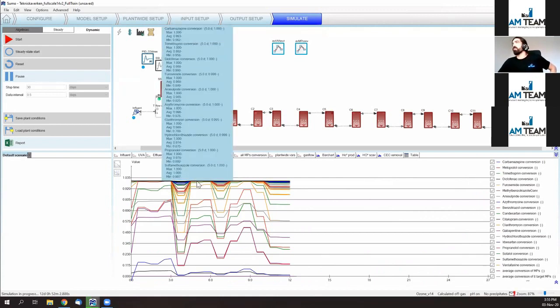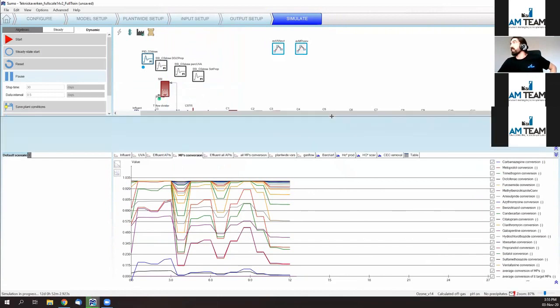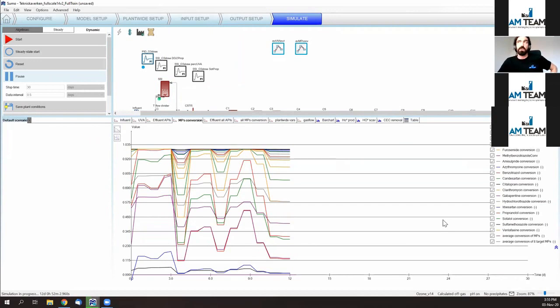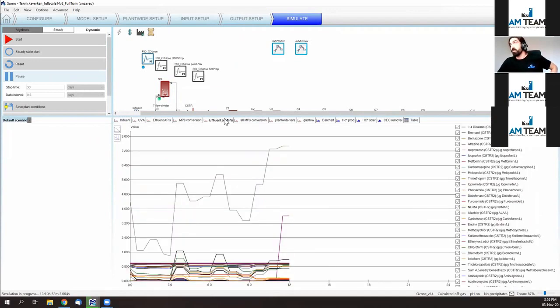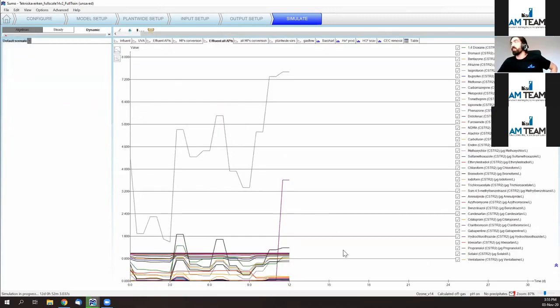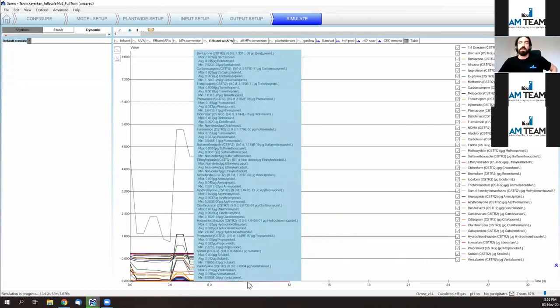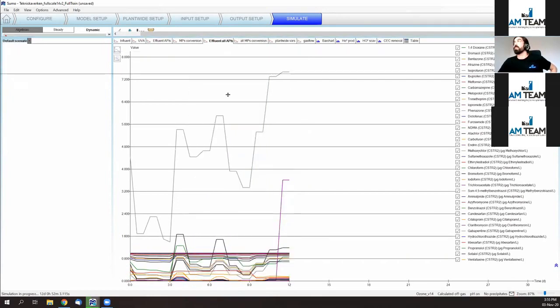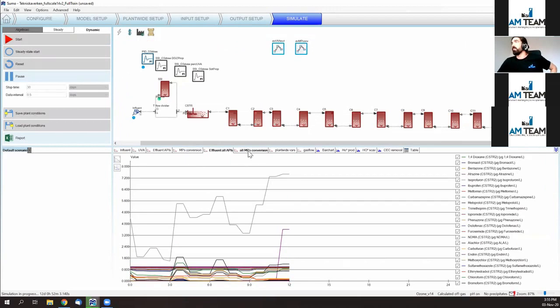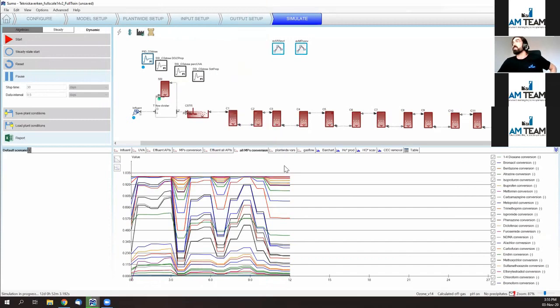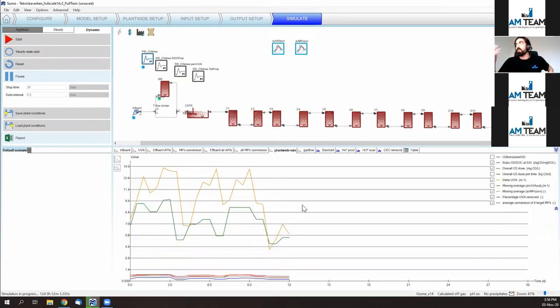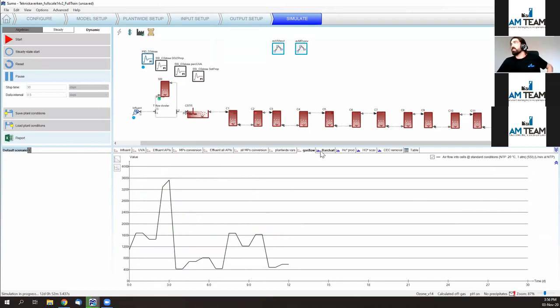You can still, as I was saying before, look at the conversion of the micropollutants that were here, to see the list of interest for this plant, but you can also look at a much larger list that we have implemented there. So you can really have a large variety of micropollutants and all sorts of compounds and intermediates that you can think of. The conversion, both concentration and conversion terms, and still the plant-wide variables. So plant-wide, what is the delta UVA you are having along the year, rather than the overall ozone dose, and so on. All right, here's some gas flow, that's some process parameters.